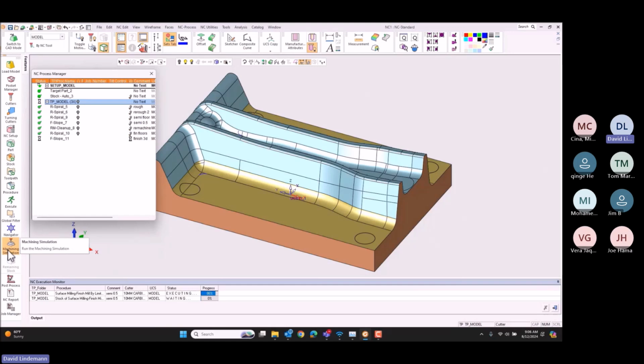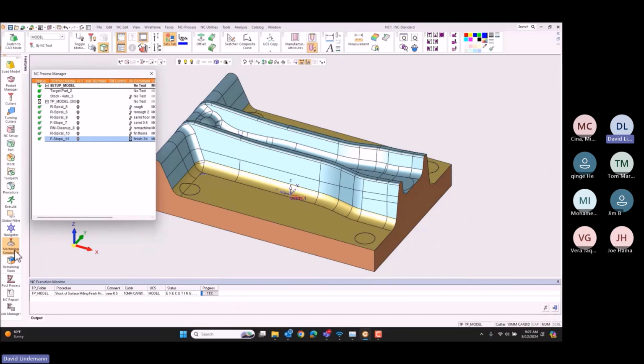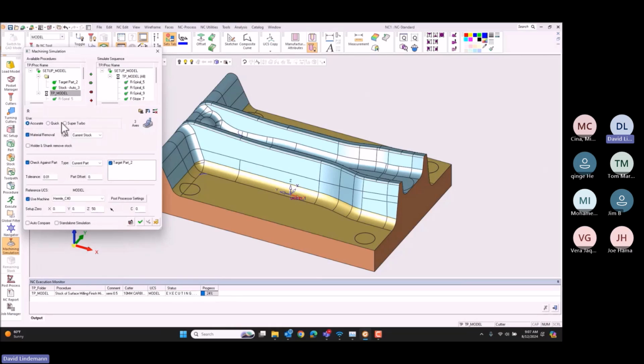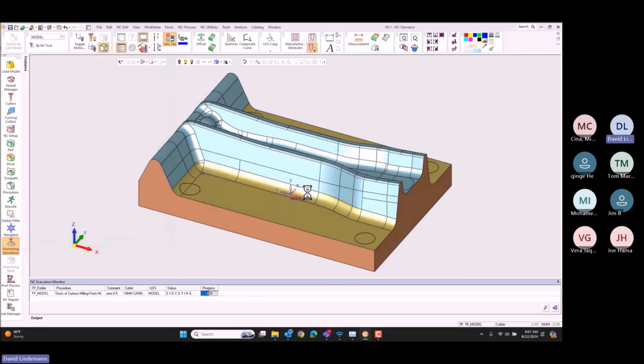Okay, just a few more seconds here and we'll have all our progression done. Now we're going to, of course, want to see, did we remove all the stock? And then our motions, are they looking good? It's always advantageous to check your stock. So now you see I'm doing the calculation that updates that last stock statement, and we'll know exactly what we have left that we need to check. Okay, so we can go ahead and bring this in to our simulator.